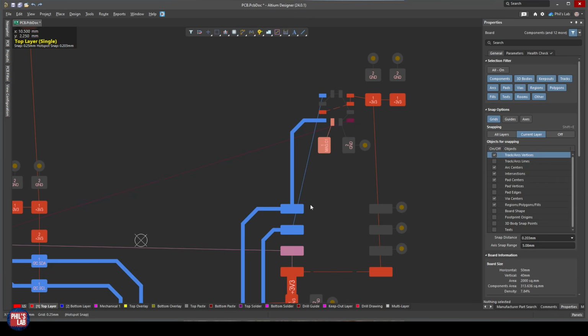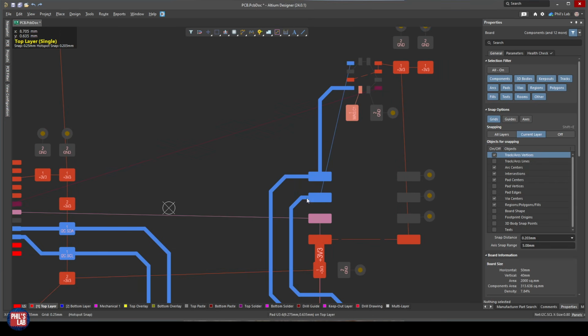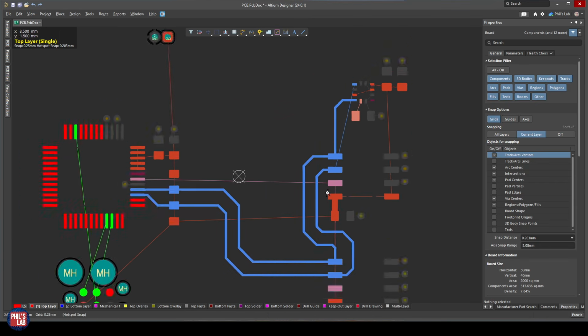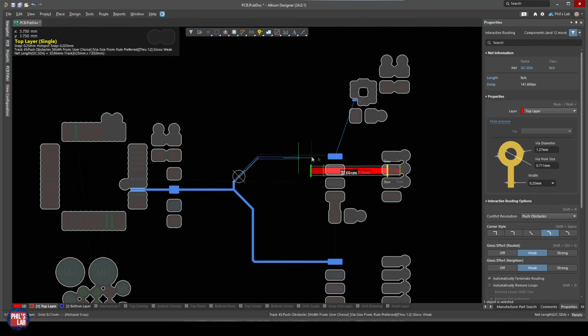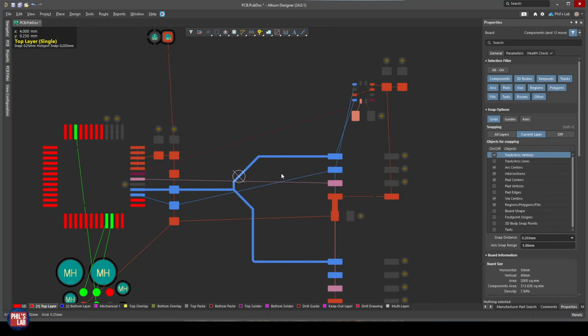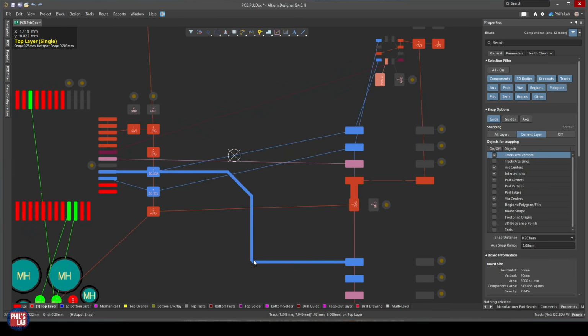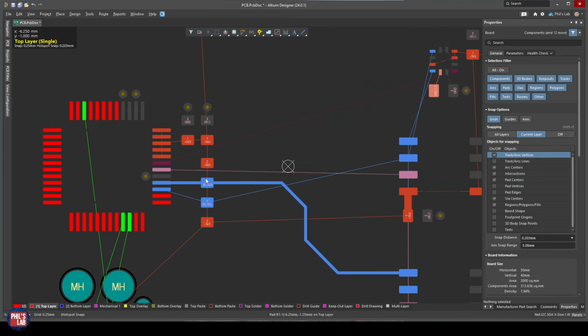It's one of a lower priority signal, typically in a design. What you still want to do is keep distance, maintain spacing, try to keep your traces as short as you can. But again, from personal experience, it doesn't really matter too much if you route through the components or if you really do these branches. If you do these branches, I'd aim to keep the branches short. That's just a general guideline. Again, you can be pretty free with I2C because they're very, very slow rise times. And typically, unless you have very, very long traces, you're very, very flexible with the routing. Make sure you keep your traces short, space them far enough apart, route through pull-up resistors, and keep distance between other components, traces, board edges, and so on.